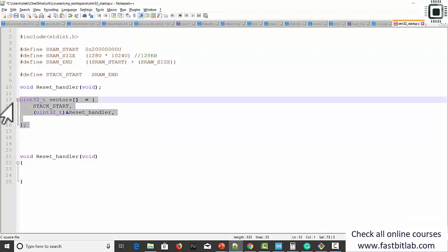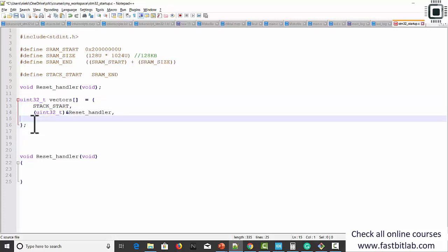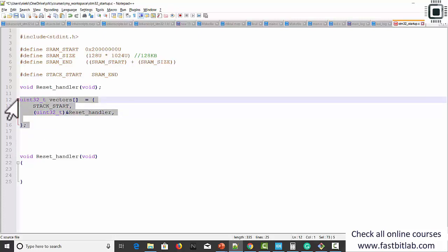This is the initialized data. The initialized data will go to the data section. You have to instruct the compiler not to put this data in the data section, but rather in a different section, which we call a user-defined section. How do you tell the compiler to move this data into a different section? That you can do by using the compiler attribute.